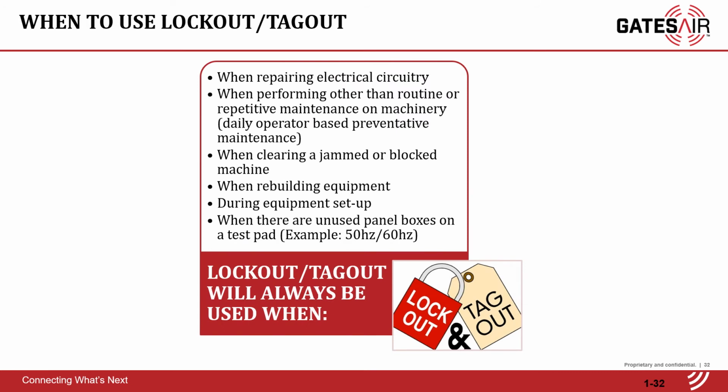Always use lockout-tagout when repairing electrical circuitry, performing other than routine maintenance or repetitive jobs, clearing jammed or blocked machinery, when rebuilding equipment, and during equipment setup. Also use lockout-tagout when there are unused panel boxes in the area.